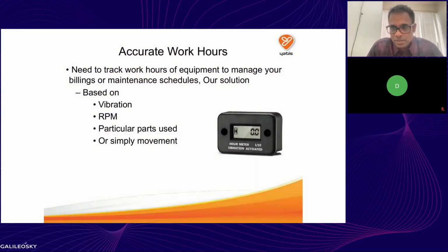Number of working hours is extremely important for mining vehicles. We provide multiple ways in which you can count that. We can configure the working hour calculations based on vibrations, RPMs, movement, or even based on some inclined sensors, certain angle changes, etc. Therefore, we can give you extremely customized reports for your equipment and vehicles based on how many hours a particular equipment has moved.